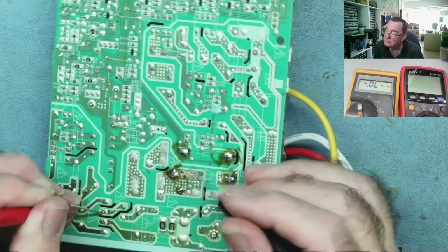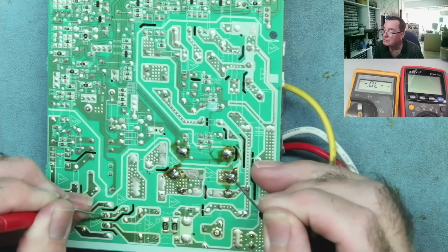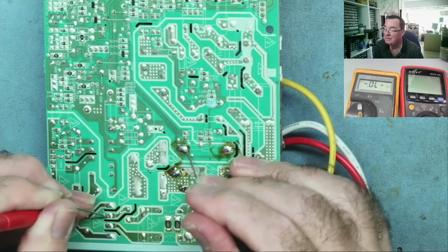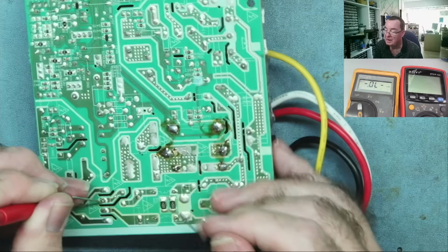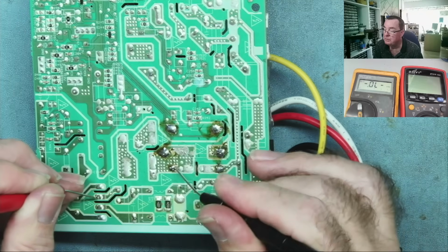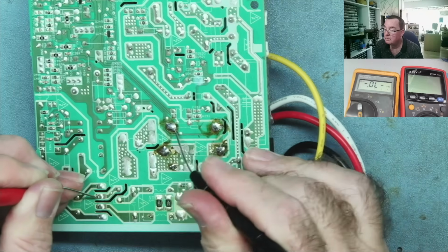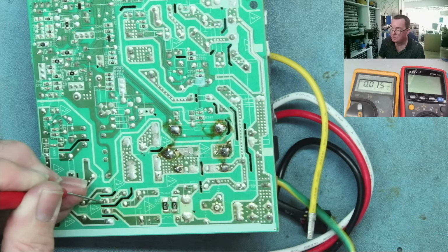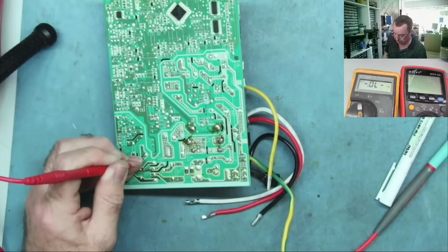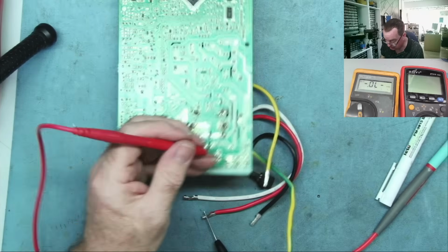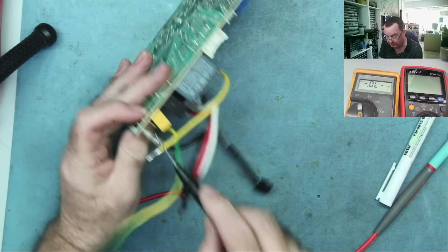Looks like this only switches on when the relay is on, which is strange because something has to power the relay, yeah? But the relay is 12 volts, this looks like a 5 volt supply. Well, what I can do, and there's no reason why I shouldn't do it, just check on these wires. Oh, okay, I've got it. So that goes to the red, okay? So I can connect my mains between the red and the spade terminal here.